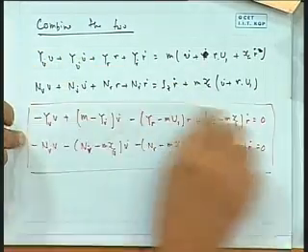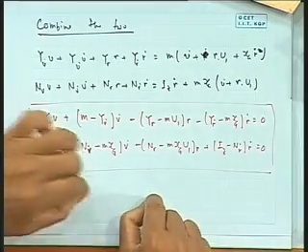That we will talk about next class, is given by the characteristic solution of this equation. Here I have got v dot, r dot and all these coefficients. I want to know whether v and r grow with time or reduce with time. I have to see, and my ship would be stable if they reduce with time. This is exactly why you need to find out the forces. We cannot simply say that the ship is stable or unstable in this case, for the very simple reason that the forces are created because of the velocity and acceleration, which are fluid forces, and it is the interplay of force and velocity that tells me whether the ship is stable or unstable.